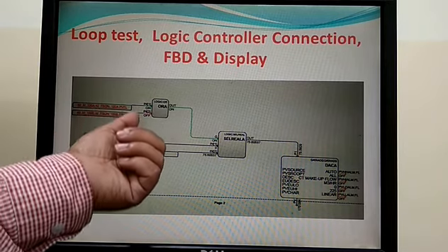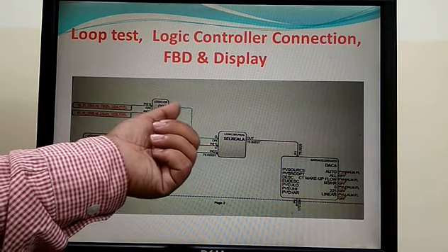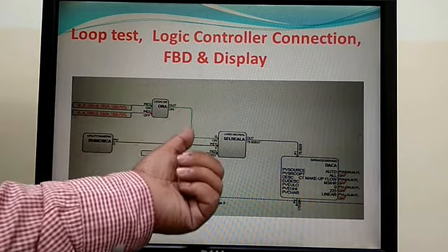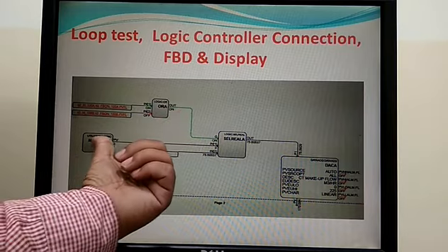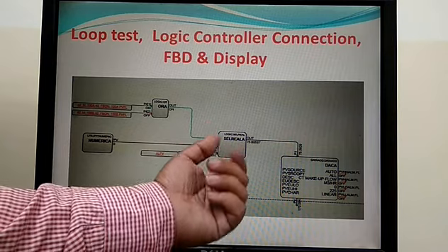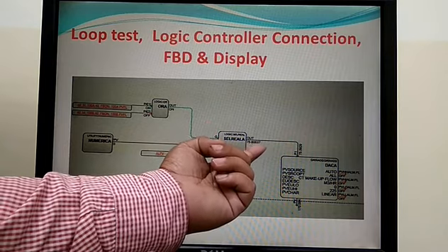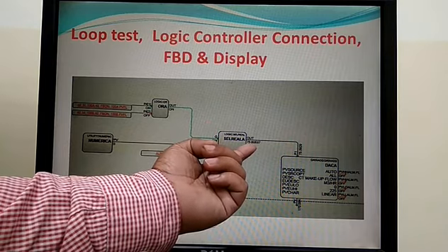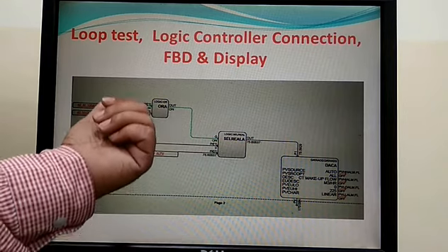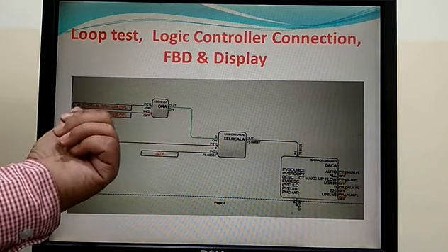After getting 1 and 1 here, it will give an output, logic OR, and after getting this green signal, which means this is high, and from these 3 values, when all 3 values are true, some output is coming out. You see 75, the process value is coming out. That means some interlocks are also there, pump interlocks or other motor interlocks.